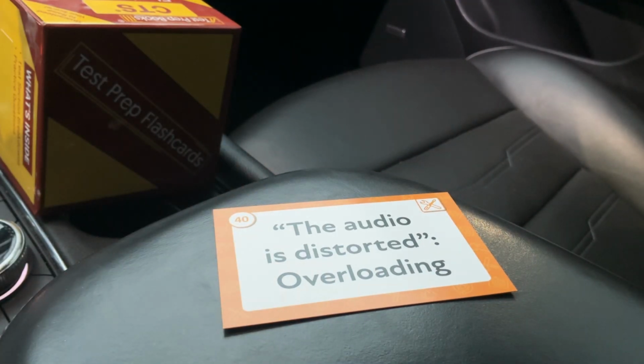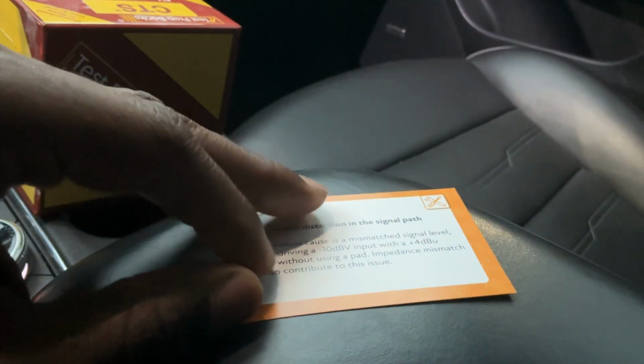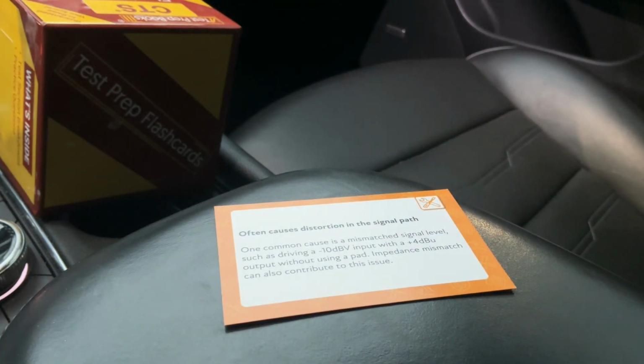The audio is distorted, overloading. Overloading often causes distortion in the signal path. One common cause is a mismatched signal level, such as driving a -10 dBV input with a +4 dBu output without using a pad. Impedance mismatch can also contribute to this issue.